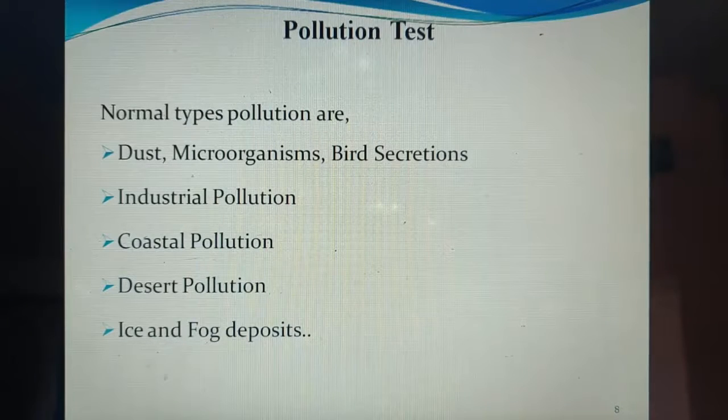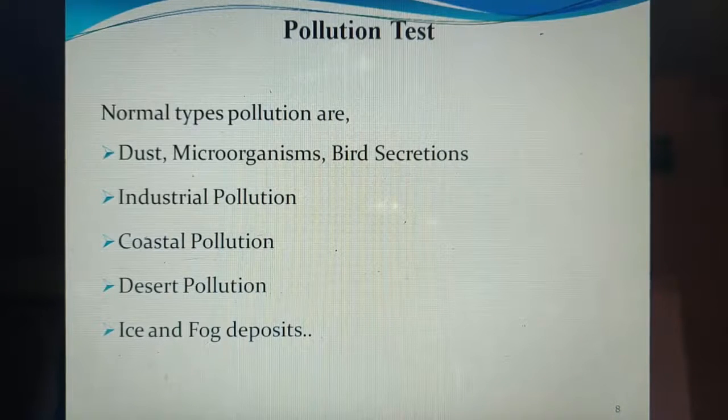In this test, the maximum normal withstand voltage is applied on the insulator and an artificial salt fog is created around the insulator by a jet of salt water and compressed air. Salinity water is used, and this water is jetted on the insulator.